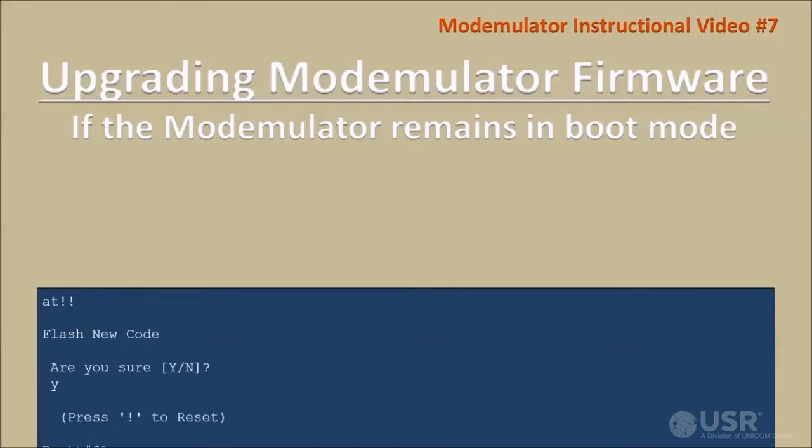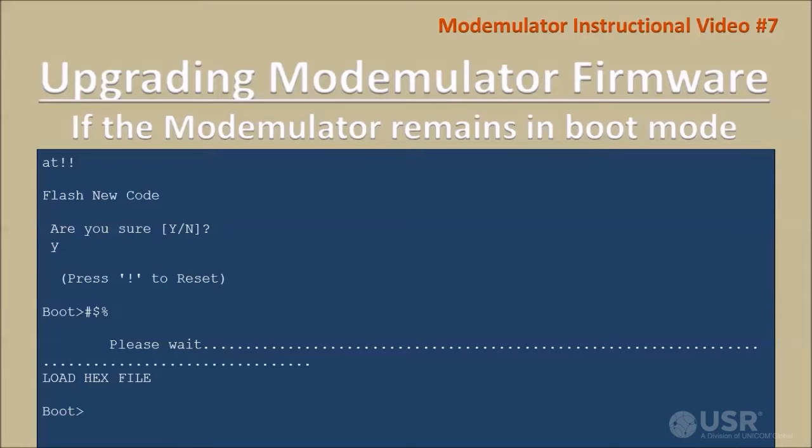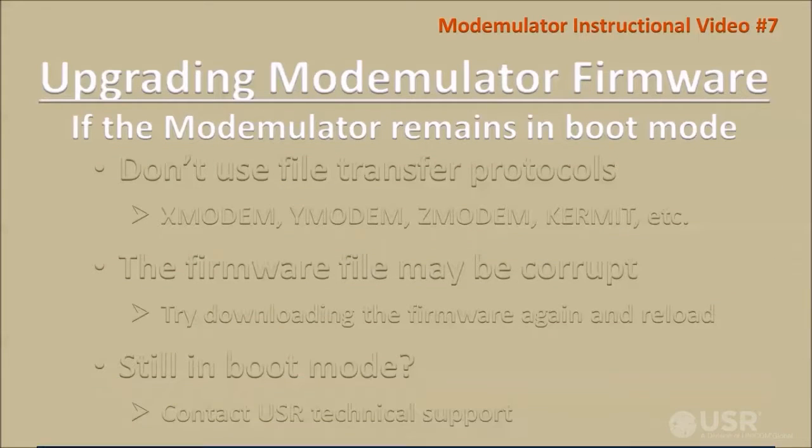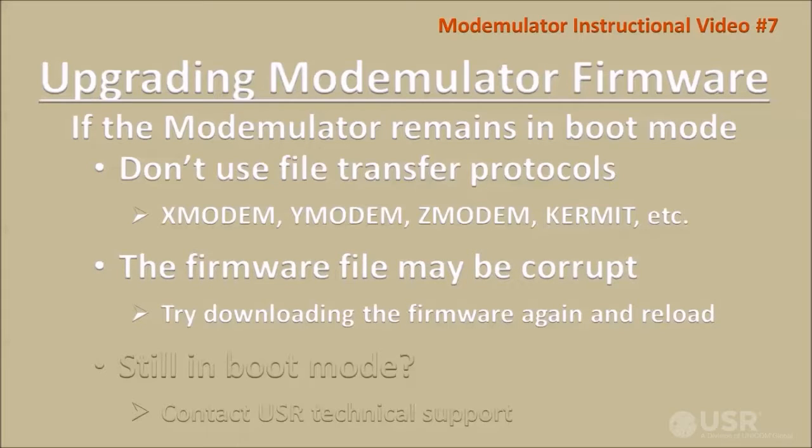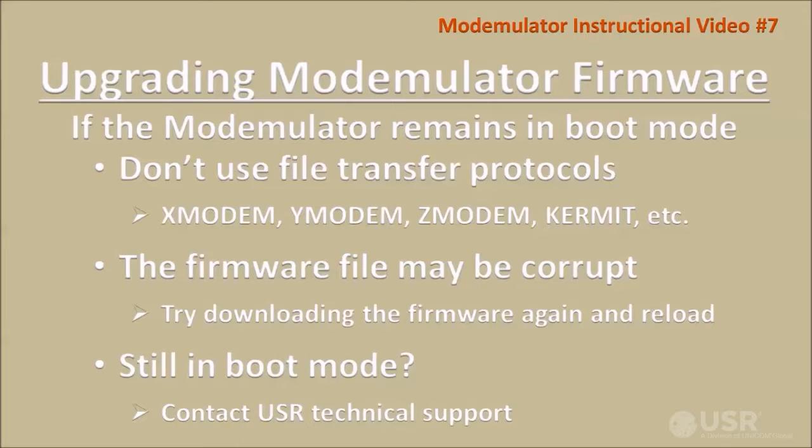Modemulator will test the checksum of the new firmware. If the checksum fails, the boot prompt will reappear. If the Modemulator remains in boot mode after receiving the new firmware, verify that the terminal application is using a raw binary file transfer. Do not use protocols like Xmodem, Ymodem, Zmodem, Kermit, or others. Or the firmware file may be corrupt. Try downloading the firmware again from the USR support page and repeat the file transfer into the Modemulator. If the Modemulator still remains in boot mode, contact USR technical support.